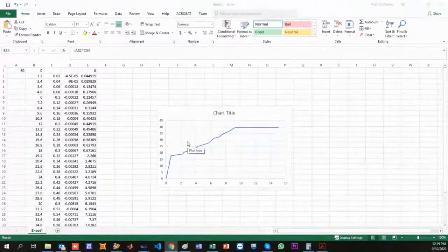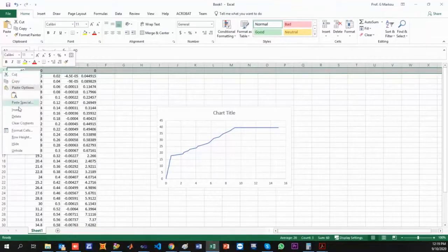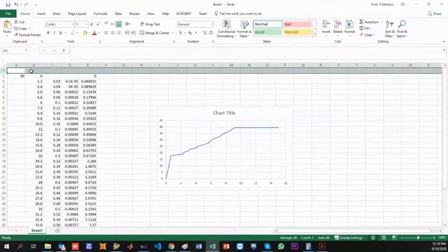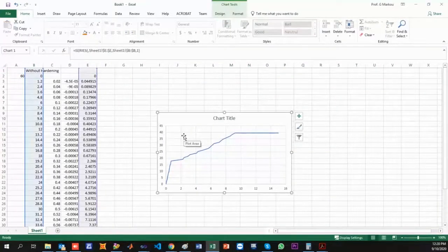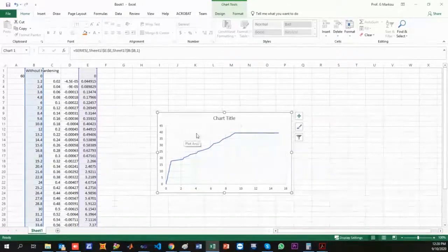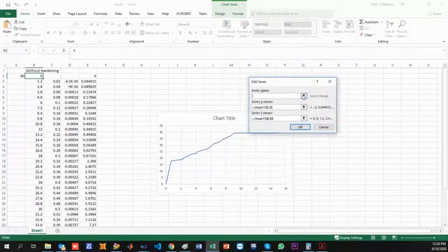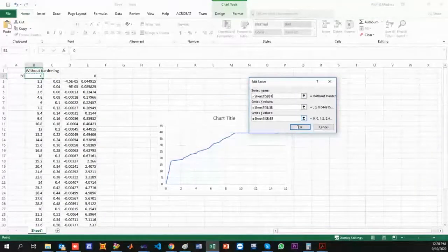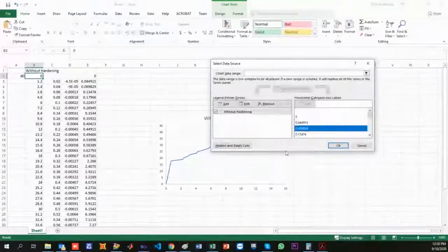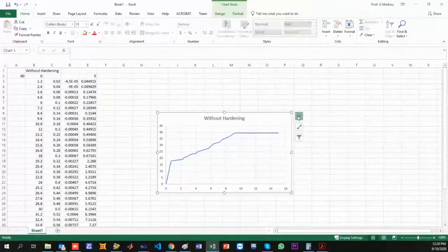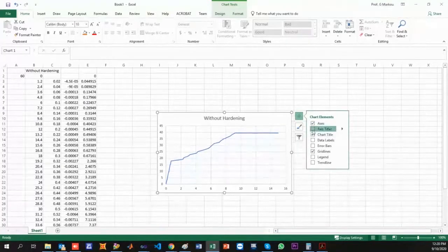All right, let me ask you something else, Greg. Would you trust more the formula or this result here? Why the result? Greg says the result. Gregory as well. Why? Gregory says taking into account each finite element. Greg says the formula is too simplified. All right, so definitely the formula is very simplistic. There is no doubt about it. So our finite element analysis model takes into consideration different phenomena that the formula doesn't take into account, including the deformation of the section, including the micro cracking, cracks, and so on, phenomena that are not accounted for when we are using the simplistic formula, right?